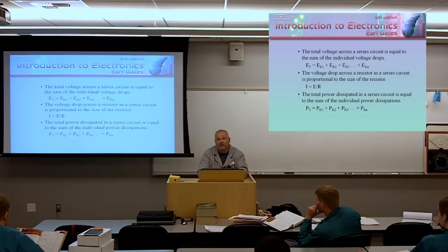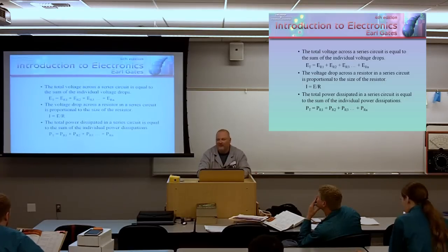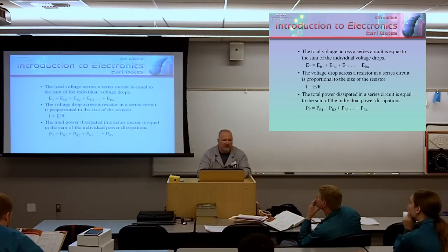So here, voltage rise, ET, or VT if you prefer, equals the voltage drops ER1, ER2, ER3. Those three voltages better equal what I put into the circuit. If not, you've got a problem. If you find where the missing voltage is, you've probably found the problem. Where was the missing voltage? Oh, it was in a bad splice. Okay, you fix that problem, boom, you're up and running.